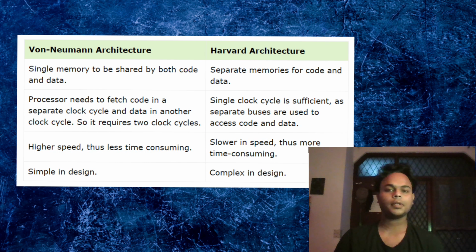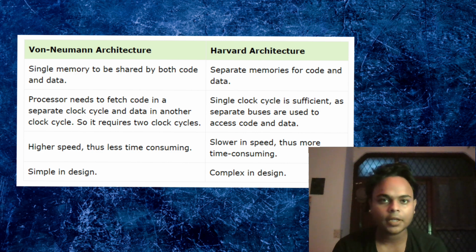And there are two types of architectures used in embedded systems, which are most common. The first one is Harvard architecture, and the next one is von Neumann architecture. The Harvard architecture offers separate storage and signal buses for instruction and data. This architecture has data storage entirely contained within the CPU, and there is no access to the instruction storage as data.